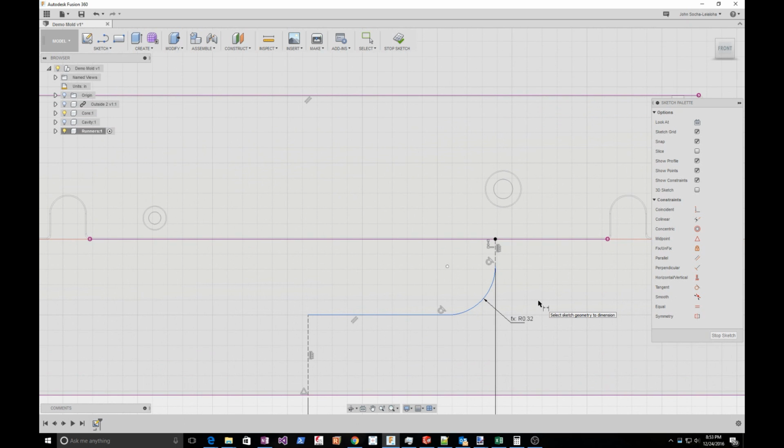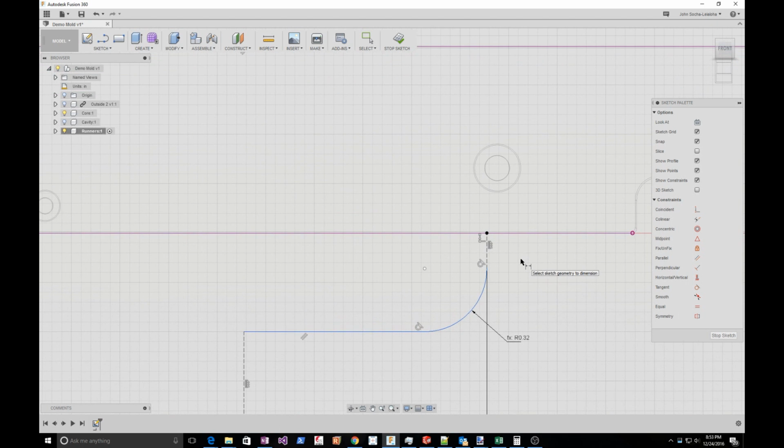So what I'm going to have on the end of this runner is a curved cap right up here. And that curve will extend out to the radius of the runner. And then I want the distance from there to be, I think, about 20 or 30 thousandths of an inch, for the length of the sprue. I have to go back and look at what I used in the past. It's been a couple of years since I created molds. But I'm going to go ahead and set that now. So I'll say that I want this to be equal to, I'll just do that so I don't have to type it, the sprue radius minus 0.03.